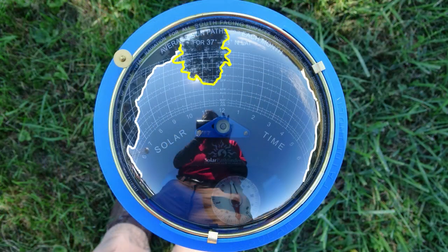In this case, we have a tree located directly to the south that's casting a shadow between 10 a.m. and 12:30 p.m. from about September to March. While this shading will certainly hinder your system production in the colder seasons of the year, the tree will at least have fewer leaves in the winter to allow more sunlight to come through.